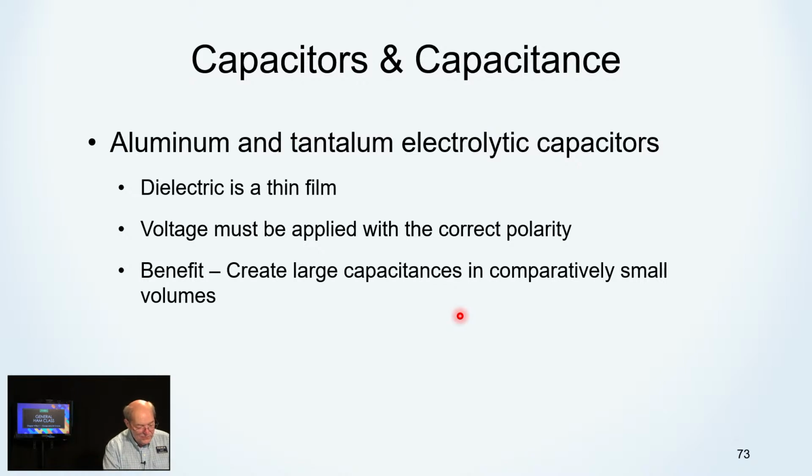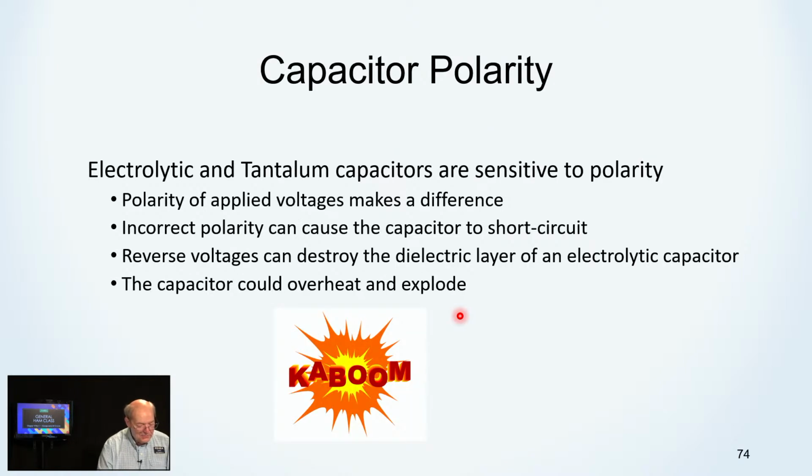So what happens if you violate the rule of hooking them up correctly? Well, that's what this is down here. It says kaboom. And let me tell you, you've never lived until you've experienced the smell of a blown up electrolytic capacitor. They're really nasty. And when they do blow up, they can blow up rather explosively.